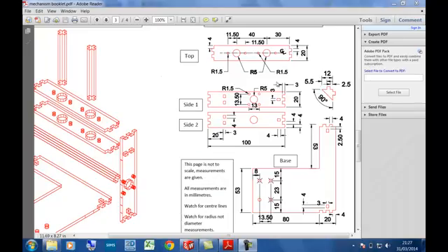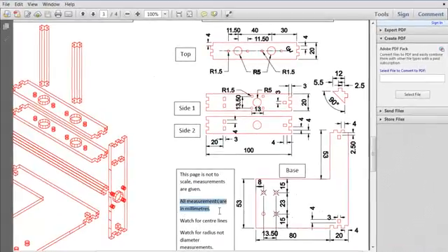So let's look at this top piece we're going to create today. Okay, so this is the top piece. As you can see, it's been precisely sketched out for you, and you're going to design this piece based on those dimensions given. All those measurements are in millimeters, as you see here. And also the radius for those circles is 1.5. Not diameters, I repeat, not diameters but radius, and the distance between each shape is precisely sketched so that we have a finished product that can fit together.